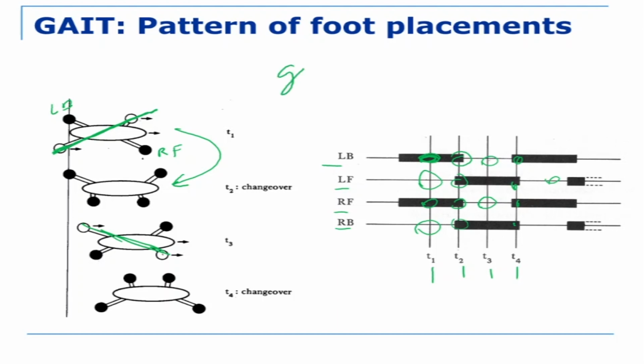So it is ground, air, ground, air, like that. Now obviously there are four legs here, right? Because there are four legs, you can either take two of them in air or you can take only one of them in air. I could have kept all three of them on the ground and only this leg goes forward. That gait is also possible.